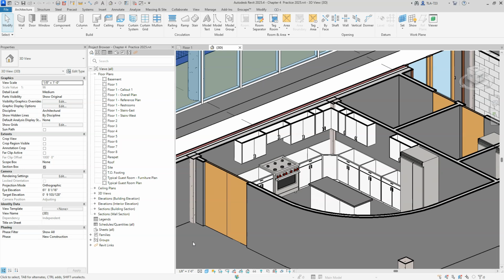And so they might start with something as small as a 9-inch wide cabinet and go all the way up to maybe 3 or 4 feet wide. But they're only going to come typically in 3-inch increments, and that's just something that is a standard across the industry. Does not apply to custom cabinets. Those can be built any size that you want, but 3-inch increments is a thing to remember.